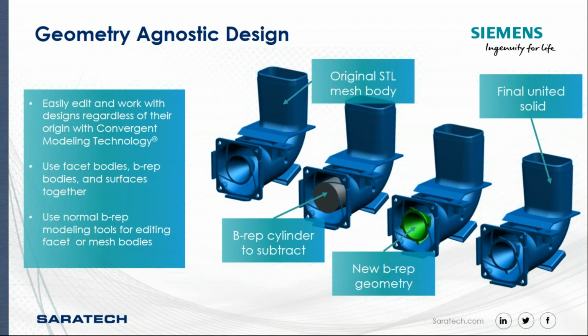So you'll see people doing this wonderful topology optimization. They'll bring that in from their external topology optimization system, bring it back into their CAD package, and then they'll use the normal modeling operations from the CAD package to totally redesign that part that they just spent hours maybe creating with CAE. And so in our system, you don't have to do that. You can use that geometry directly and then use CAD operations on top of that geometry to modify it as you need to.